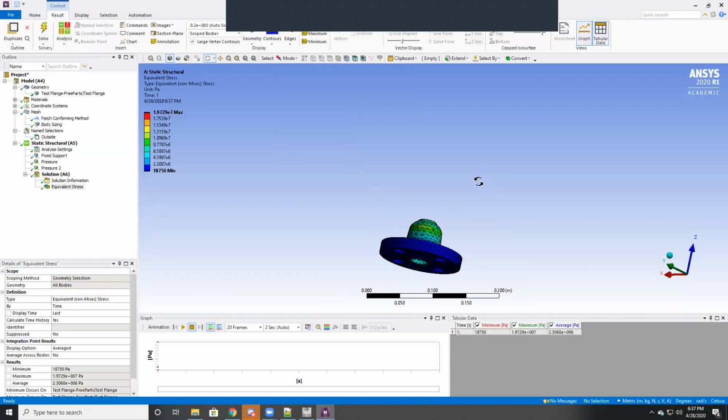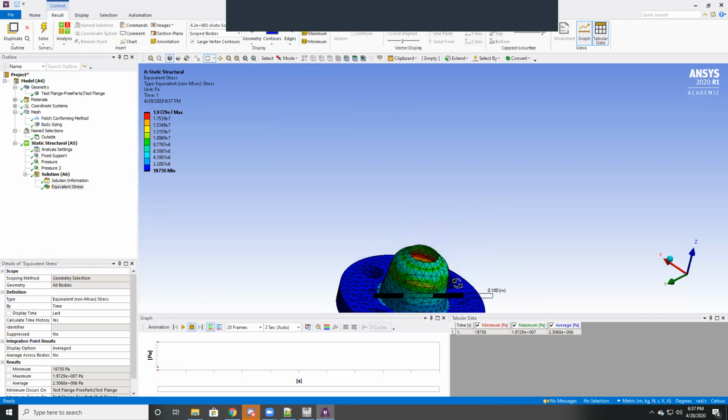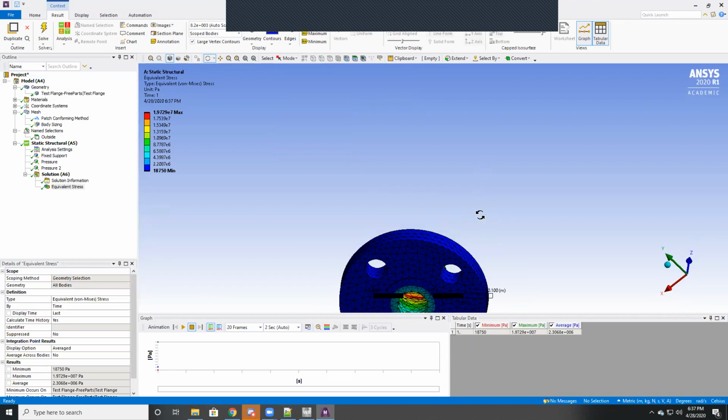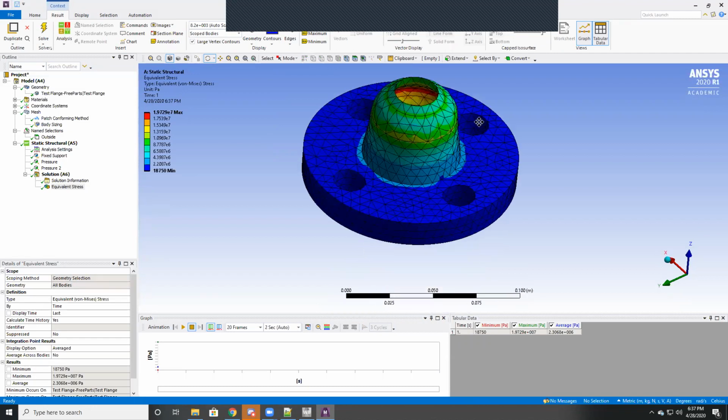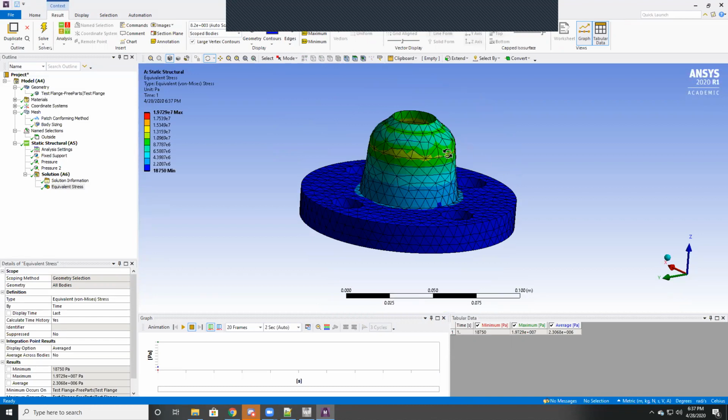And it shows a very dramatically overscaled image of what is happening to the part. So the flange itself is not bulged out this much. If you actually did this test in real life, it does not look like this. However, in order to actually emphasize where you might have weak points, they bulge it out more, those points that have more strain.